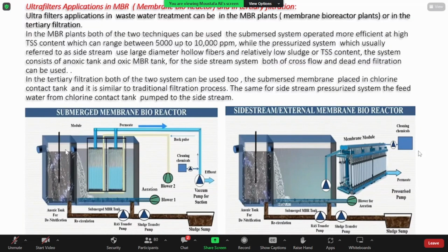So as I said, the wastewater is treated in this anoxic zone for 1 hour for the process which we call denitrification, the removal of nitrate and nitrite. After that it is displaced by another amount of raw sewage. It's a continuous process, as we know. Raw sewage enters and pushes the wastewater, which has already passed the anoxic process, to the other compartment or chamber.